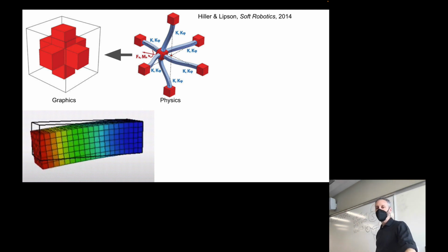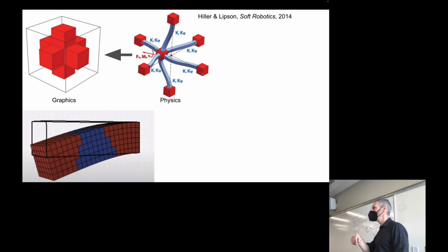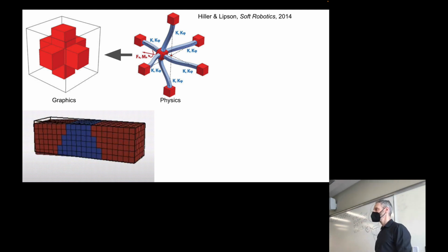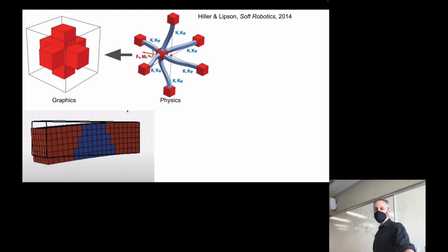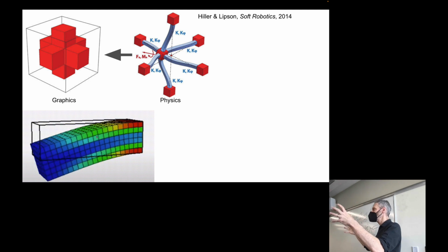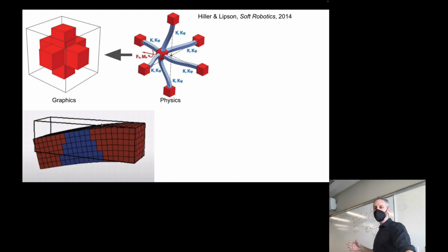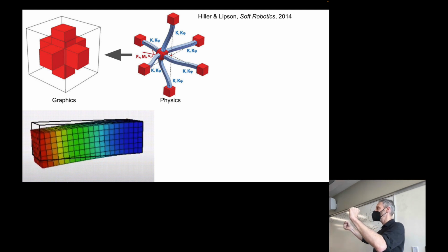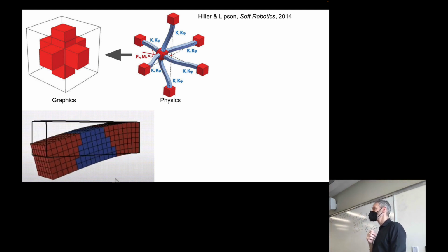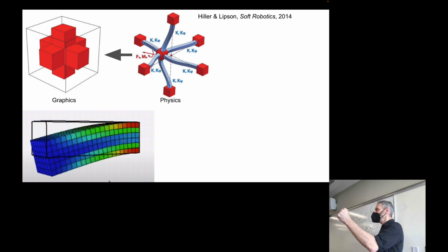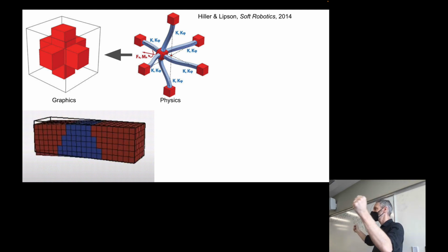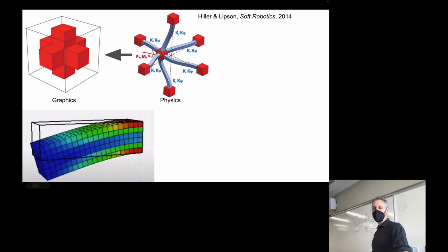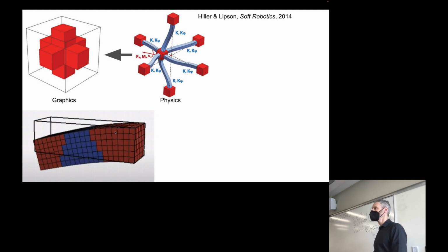And we've got a whole bunch of these beams. We can set different values for different beams, which when we put all of this together creates a material that has interesting material properties. Everybody see that? So in my little GIF down here, the blue voxels are relatively stiff. You could think about this as steel. All of the little beams that are connecting neighboring blue voxels together are very stiff. They're resisting all 3 of these different ways of relative motion between neighboring blue voxels. The red voxels are also connected with beams that are much more accommodating. They allow much more translation, shear, and torque of the neighboring red voxels. What happens where we have steel connected to rubber, blue connected to red?